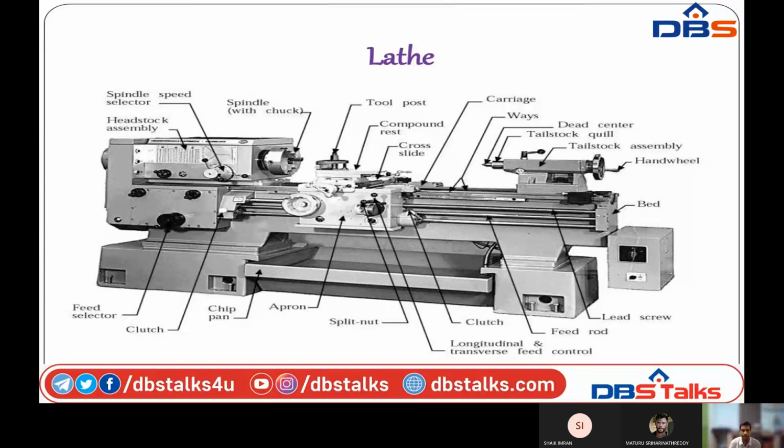Next, the hand wheel of the tailstock to move in the forward direction or backward direction. Next, these are all the main parts of the lathe machine. But the main components of lathe machines are two centers, the headstock and tailstock. Next, the carriage part. The carriage consists of the tool post. In the tool post, we set the tool and give the feed by using the feed rod or hand wheel.